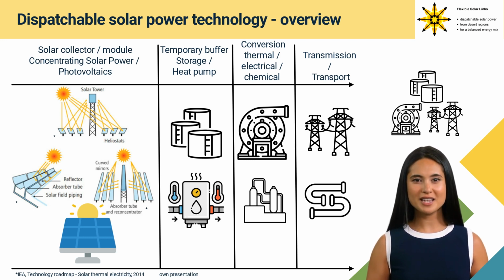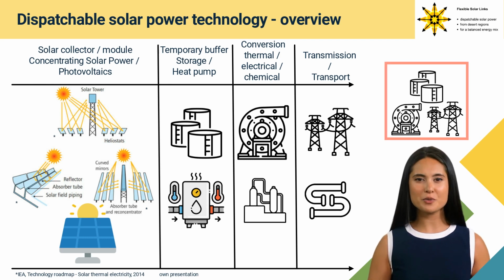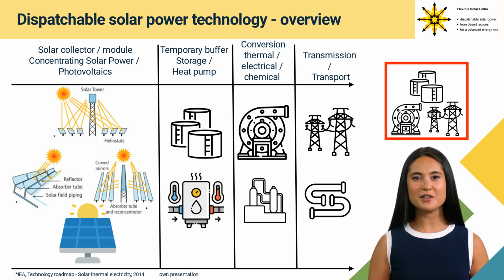However, the conversion into chemical stored energy has a physical disadvantage due to a low efficiency factor. Providing 1 kilowatt-hour of chemical energy for fuel production needs around 2 times more energy than providing 1 kilowatt-hour electrical energy. This results in the construction of around twice the amount of power plants. In the following we focus therefore only on the provision of electrical energy for the electrical supply system. However, using the advantages of each technological component in a specific mix can lead to synergies and therefore to a win-win situation benefiting from the versatility of a technology combination with different use cases.